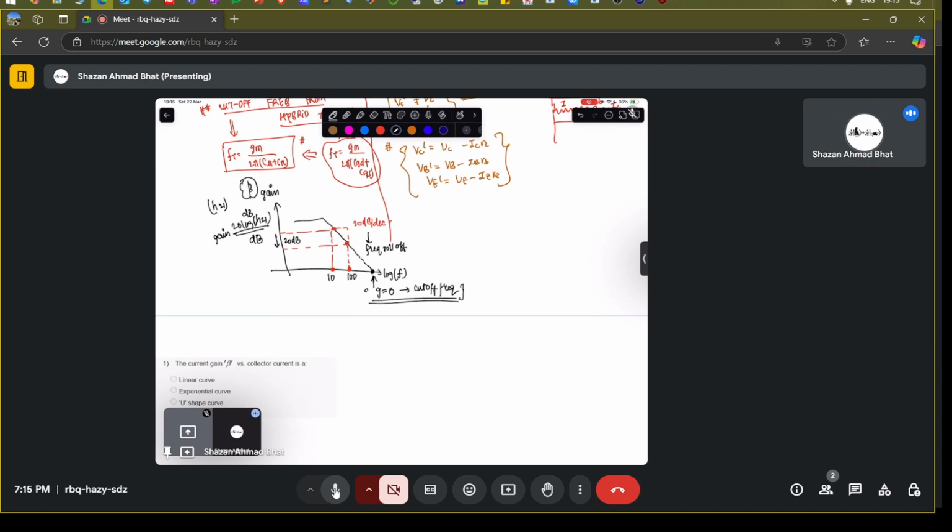Okay. So it is the maximum frequency at which your gain drops to zero. It's the maximum frequency which you can give to a system, at which, in the log scale, the decibel scale, the gain drops to zero, which is 0 dB. The gain in decibels will be 0 dB. That means IC divided by IB will be equal to 1, basically. So that's what 0 decibels means.